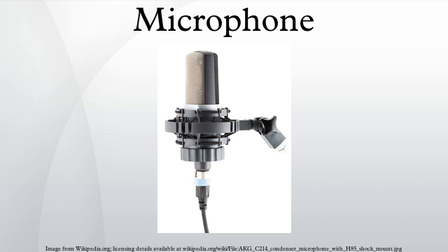In a more robust and expensive implementation, the returned light is split and fed to an interferometer, which detects movement of the surface by changes in the optical path length of the reflected beam. The former implementation is a tabletop experiment. The latter requires an extremely stable laser and precise optics. A new type of laser microphone is a device that uses a laser beam and smoke or vapor to detect sound vibrations in free air.